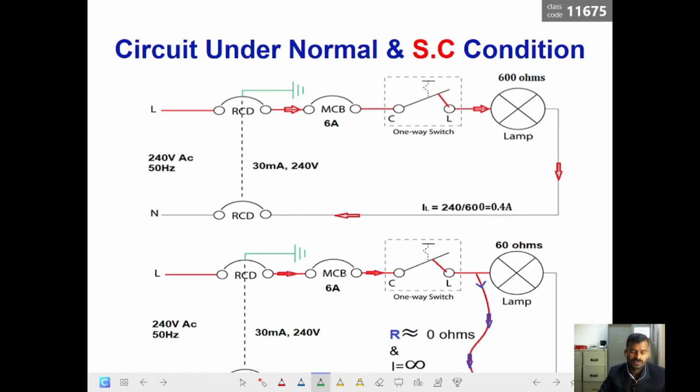Usually, how do they design the MCB? The MCB or the fuse should be the weakest point in the circuit, so it should open first, and then we will have the conductors, and then the load. Usually they see what the load current is, and then they multiply it by 1.5 to obtain the rating.